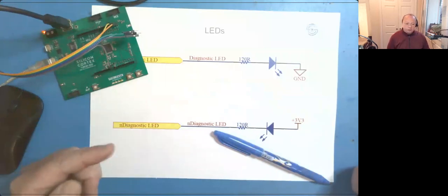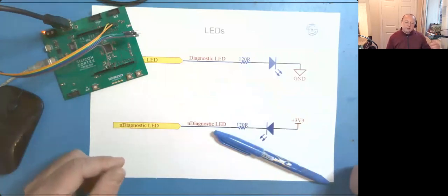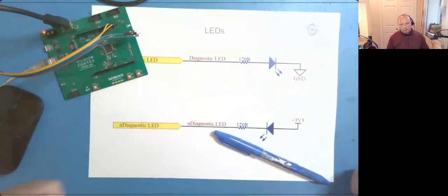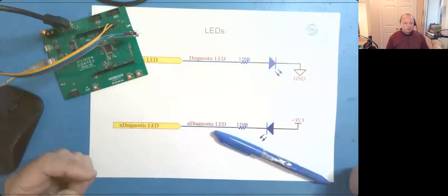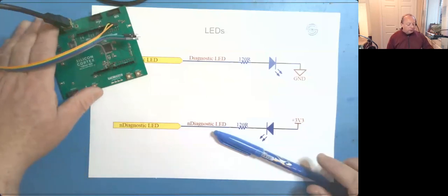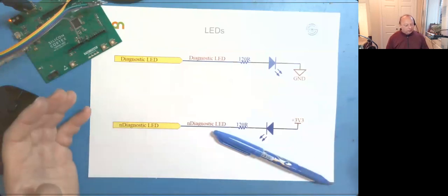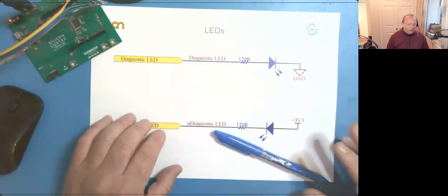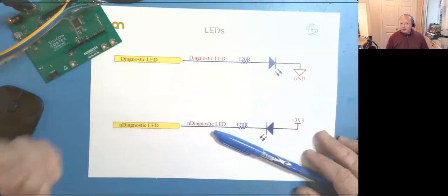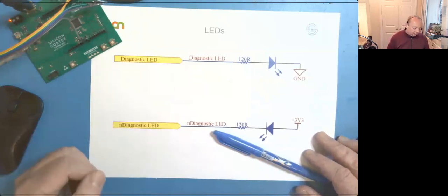And of course, I also tend to use LEDs almost like a watchdog. So maybe at the end of the program, I might have an interrupt before it goes back to the beginning of the program, just to blink an LED, just so I know it hasn't hung in real time. Because with the Arduinos and Mbed for the ARM stuff, there's precious little in there to tell you whether your code is going to hang or not. So I always put LEDs on my boards.